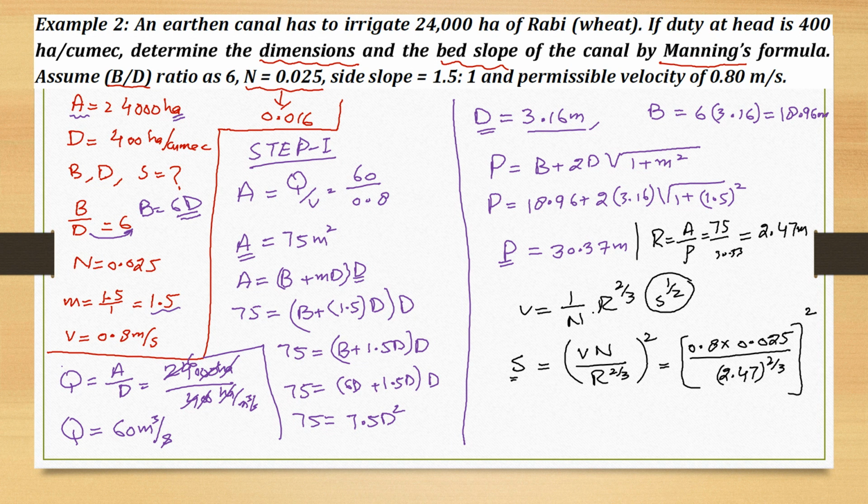So if we solve this equation, we get a value of S in fractions, but we will write the value in S by D units, means in fractions, ratio, means it will be in 1 over 8347, means if we move 8347 meter horizontally, then we will get a distance of 1 meter vertically.